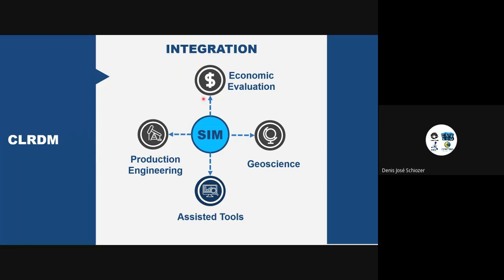And also, many companies don't have economic evaluation integrated with reservoir simulation, but for us, it's very important because all the decisions we are going to take using reservoir simulations will involve some kind of economic calculation. For example, if you want to inject a polymer in a reservoir, we have to know how much the polymer costs, how much we will improve production if we inject the polymer and so on.